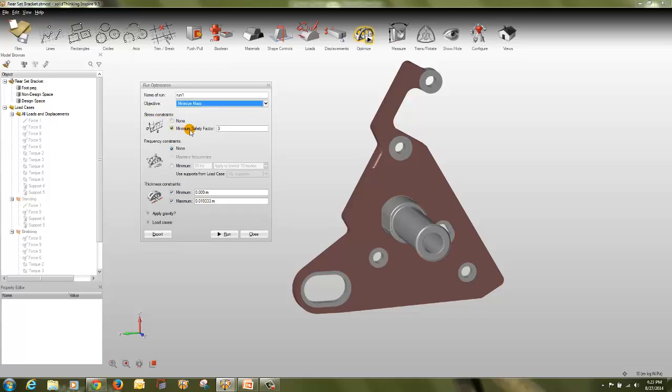Global stress constraint can be applied to limit the maximum stress in the model, and is used when your optimization objective is to minimize mass. Inspire analyzes the material used in the model to determine which has the lowest yield stress, then divides it by its minimum safety factor. The higher the safety factor, the more material will be added to the optimized shape. To limit the overall stress in the model, stress constraints are automatically enabled when minimizing mass.